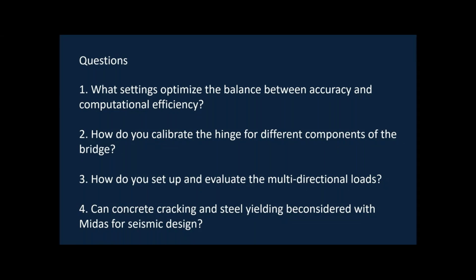So the ideal plastic hinge data is for one particular section. If it's a different section, not a normal section, then proper calibration is required from the moment curvature curve to capture those results. But for regular sections, a bilinear type of plastic hinge is okay to be used.